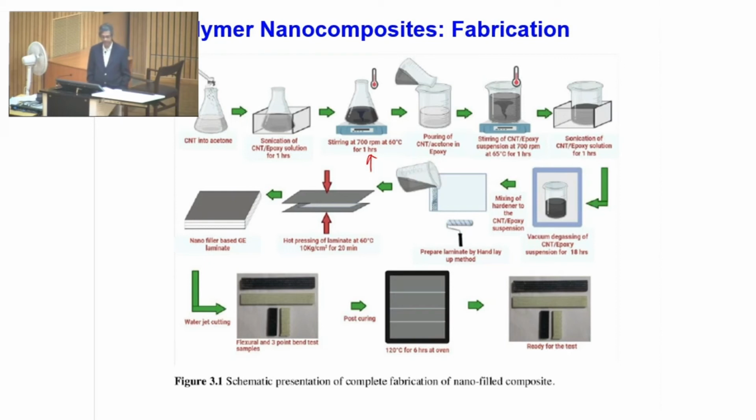In polymethyl methacrylate or PMMA polymer nanocomposites reinforced with alumina, modulus decreases due to weak interaction between the alumina and the PMMA. Whereas if you use polystyrene nanocomposites reinforced with silica, then modulus increases due to strong bonding. So bonding between this second phase and the polymer is very vital. Another advantage of using nanoparticle reinforcement is that their size is smaller than the critical crack lengths typically found in the polymers. As a result, nanoparticles provide improved toughness, very high toughness and strength.